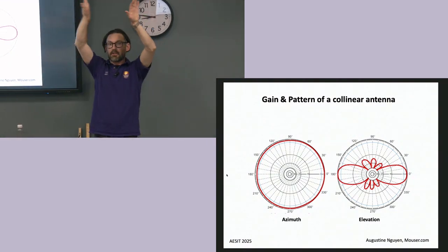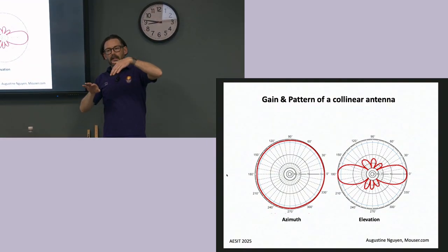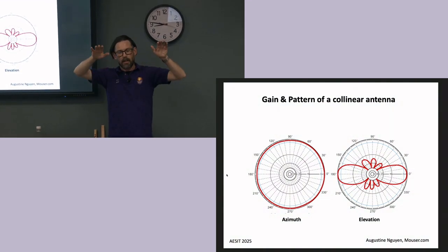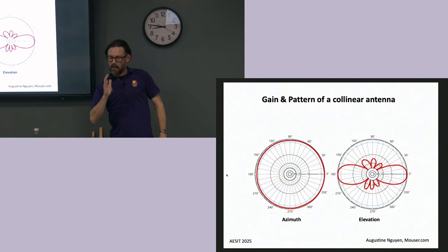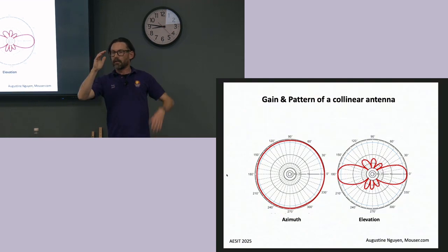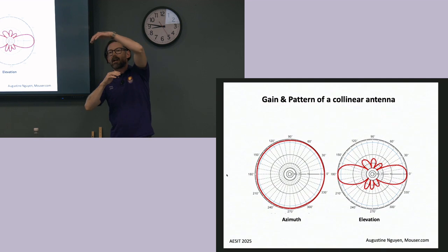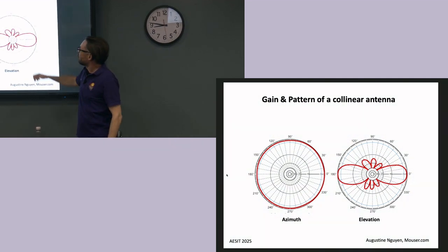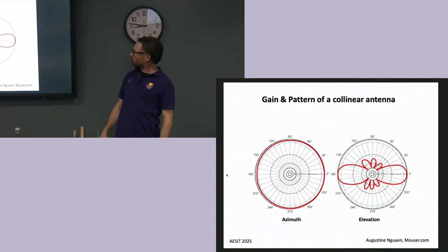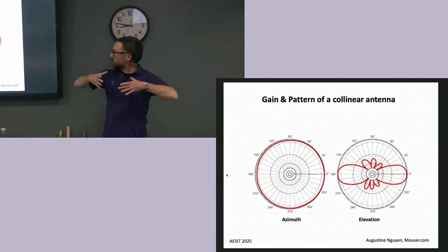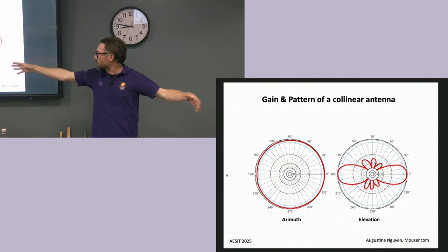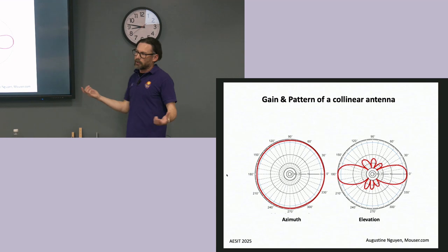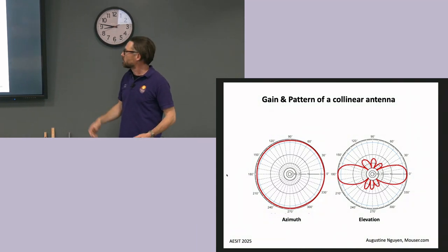But in all these other directions, they'll add together in such a way that the trough from one cancels the peak from another. As this antenna sends out a trough, a low point, this one sends out a high point, and those cancel out to be nothing at this angle. So collinears give us even more gain out towards the horizon, but not sending anything down to the worms or the clouds, where probably there's nobody walking around with a handheld to hear them.